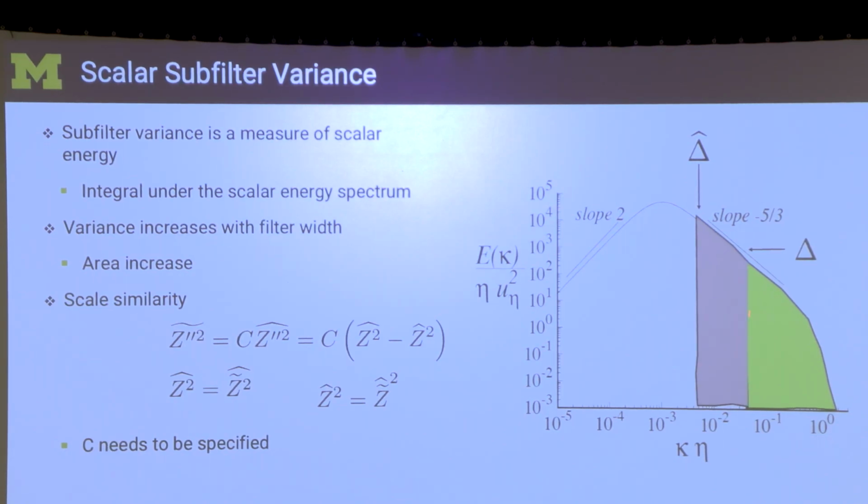So what I do is this. I have all of these scales in my simulation because I'm resolving all of these scales. So I go a little bit coarser, up to delta hat. Now I physically filter the LES solution at every time step. Now I've removed all the scales below delta hat from the simulation. And looking at what I have not accounted for, the difference, I can now predict what that yellow box is going to be. So by knowing what that purple box is, I can figure out what the yellow box is going to be. This is the whole game.